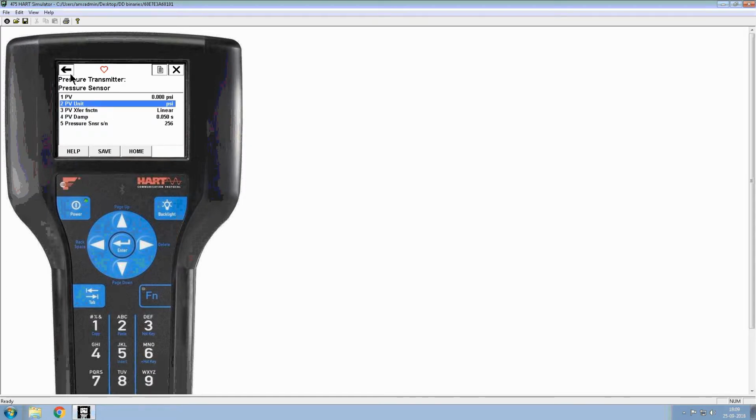The second item is labeled ranging. The first 3 parameters provide the information about the sensor lower limit, sensor upper limit and the minimum span allowed between the upper and lower range values. The next 2 parameters can be used to set the upper range value and lower range value respectively. Refer to section 3.2.2 in the IOM. The details are under re-range with a field communicator only.